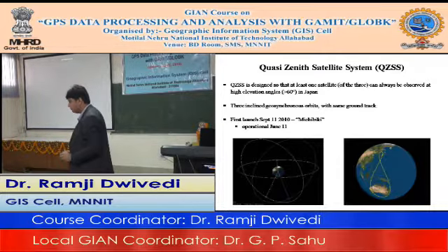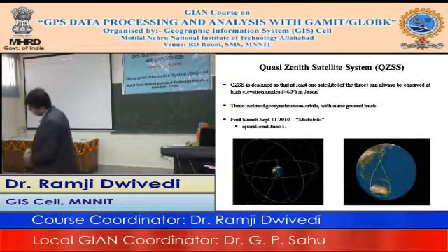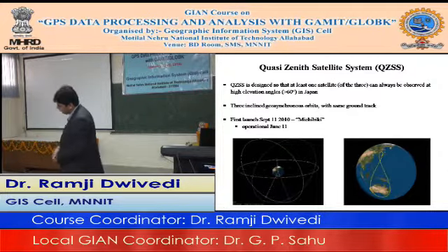So generally, whenever we put a base station at the rooftop of this building, and then we do a survey in this campus, we get control points in this campus, then it will become stop and go, and not the rapid static.